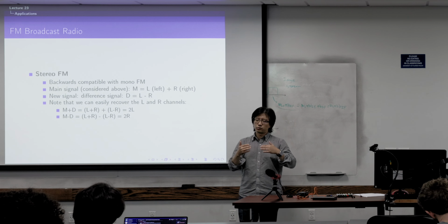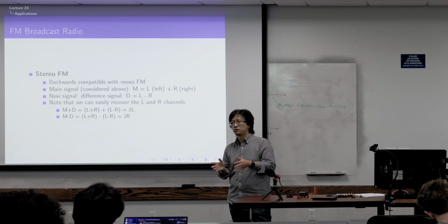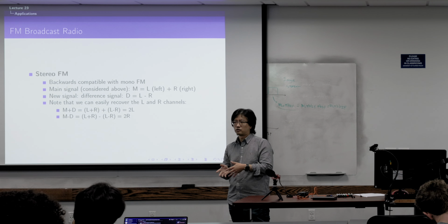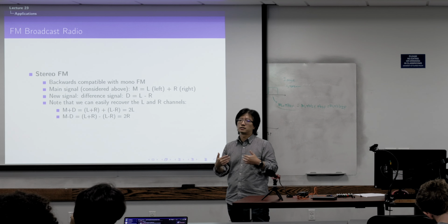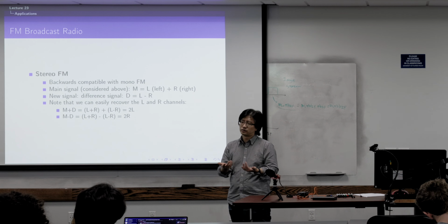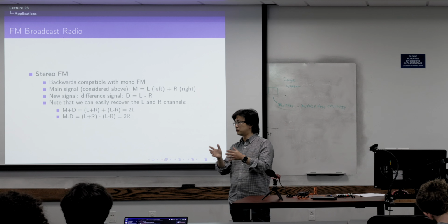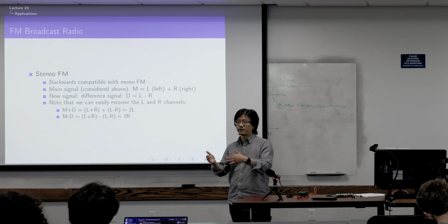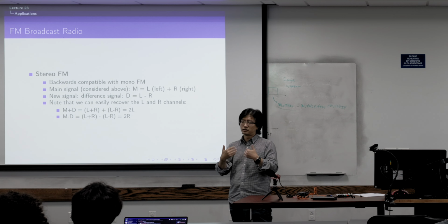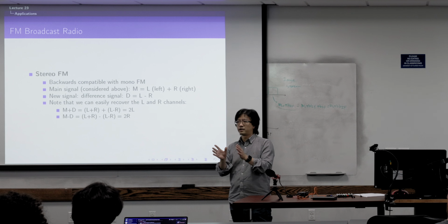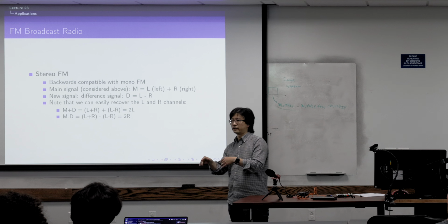So we transmit. Oh, one thing is that we need to make it compatible with the mono audio. To make it compatible with the mono audio basically means that we need to transmit a mono audio, and make it so it can be demodulated at the mono audio receiver. And then we transmit the difference between the mono and the stereo. And if you can demodulate the stereo signal, then you need to demodulate the additional part. Does that make sense? Okay, that's how it works.